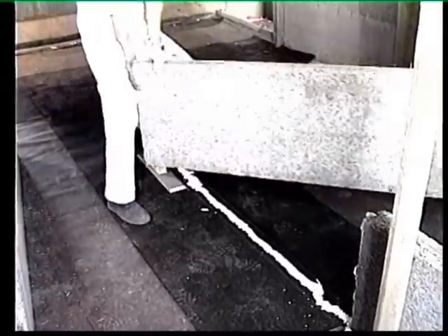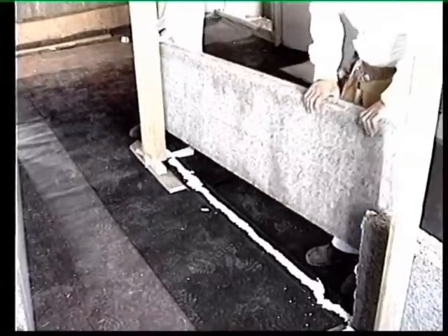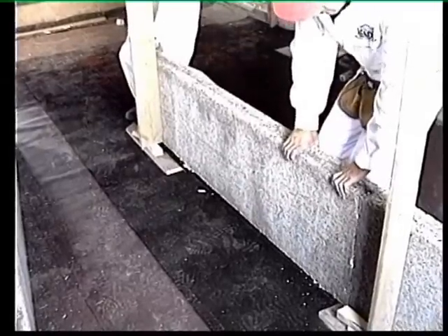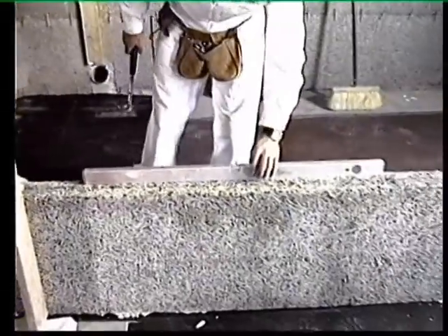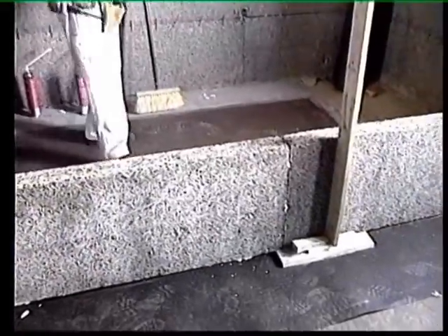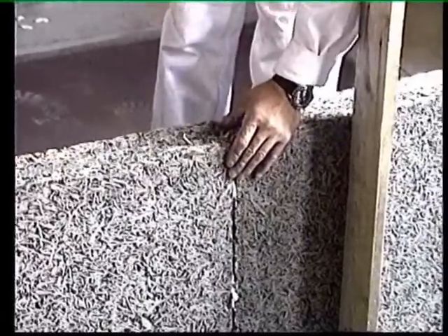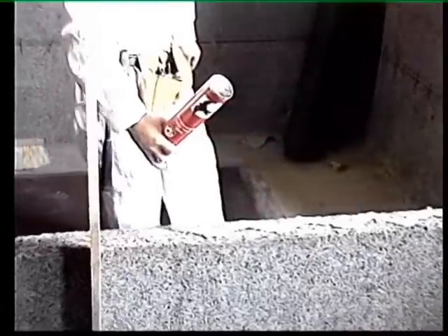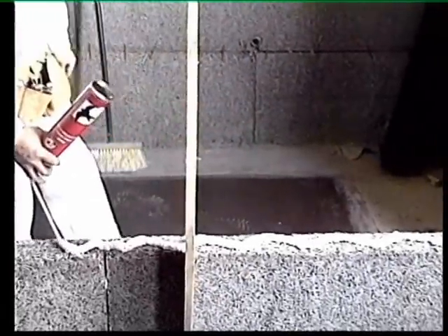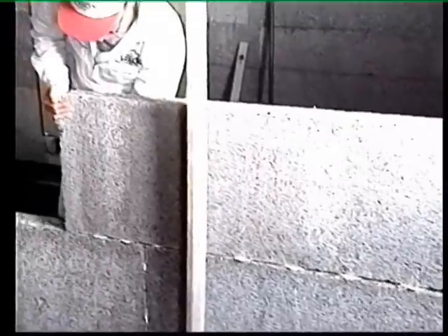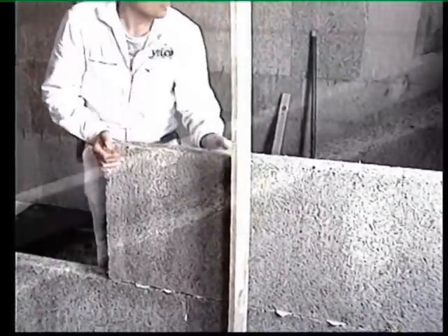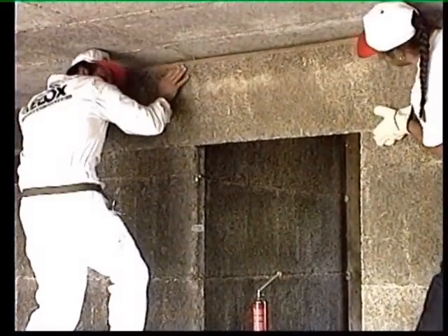Polyurethane foam or other suitable fast-drying adhesive, or cement-based adhesive, is used to join face and loading joints. After the walls are leveled, we recommend securing joints to prevent the boards from moving during construction. Velox partitions are joined together using a dry method. The boards must therefore be staggered along the face joint, even in corners. Whole boards with the corresponding cutout must be installed over openings.